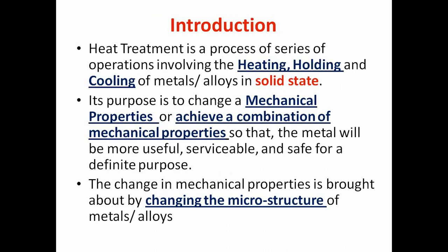Then if you observe the definition, heat treatment is the cyclic operation of heating, holding followed by cooling of castings in solid state only, because heat treatment procedure is normally carried out after the castings are solidified. So it is a process of heating, holding and cooling in case of castings in solid state only, not in liquid state.